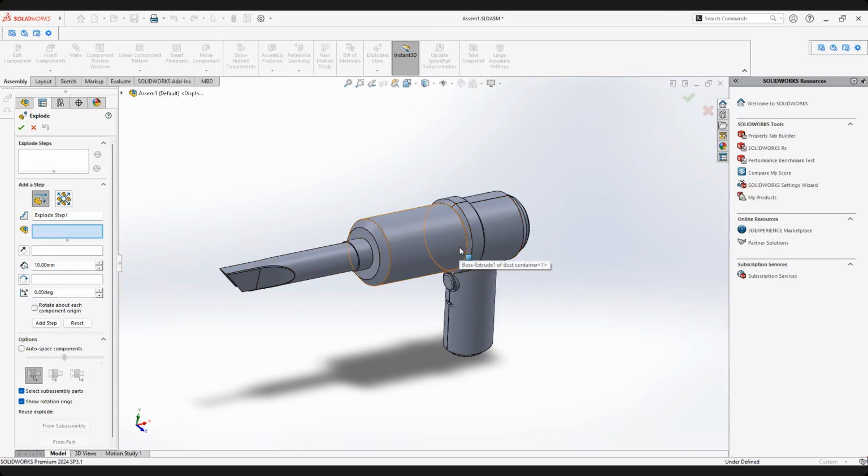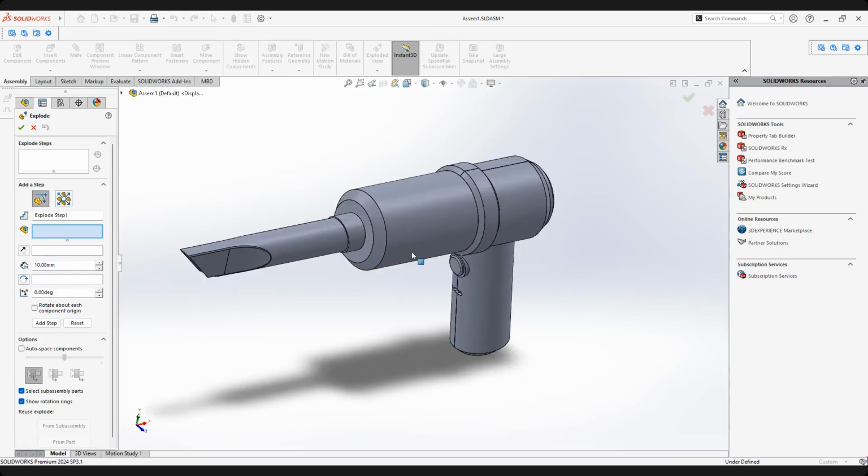Because for you to do an exploded view drawing, people in the assembly line, and also people who want to read your document, your engineering drawing, they want to look at the exploded view. They better understand how the parts are functionally related to each other, and the position of each part relative to the others. So you can show the path of how the parts will be assembled and disassembled. If you show just the full assembly like that, people cannot understand.